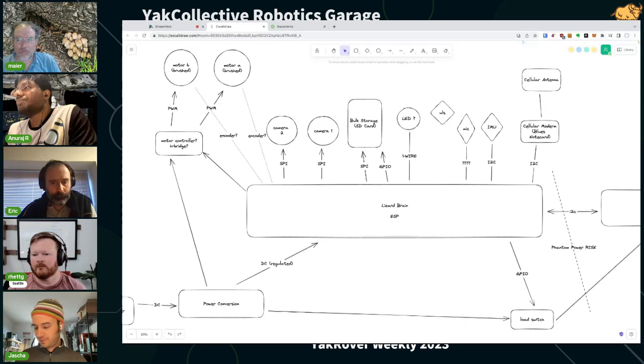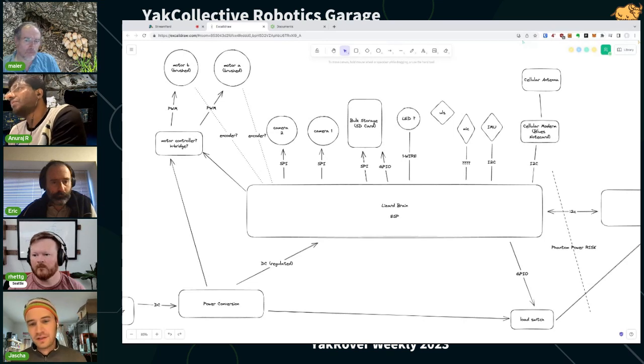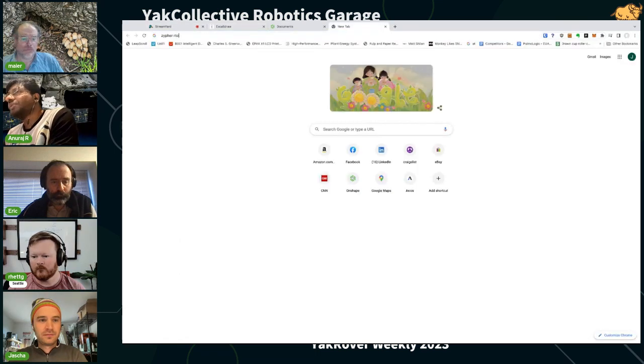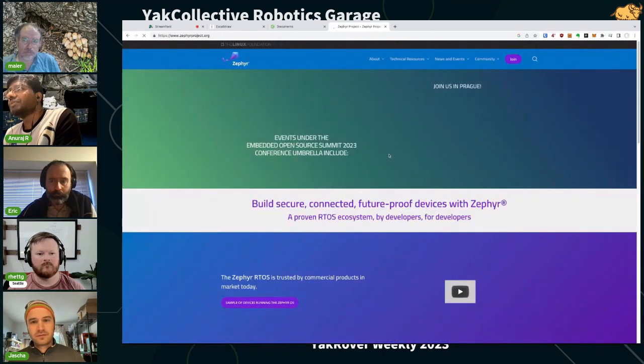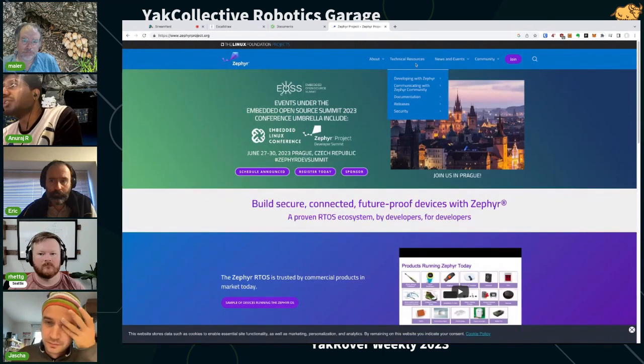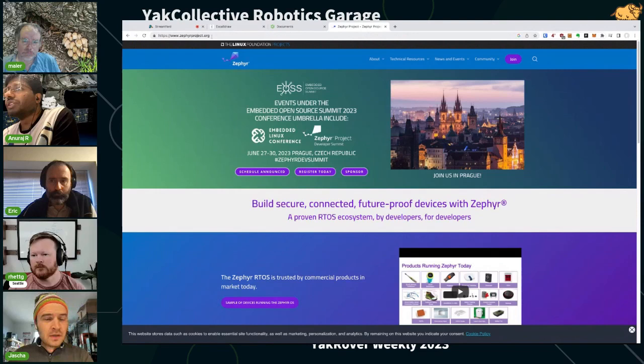It's on the silicon. Yeah, I'm okay with the ESP. The big thing is if we want to use Zephyr, I know Zephyr has limited support for ESP. They just started using Zephyr last year, so many of the drivers might not be ported to ESP.